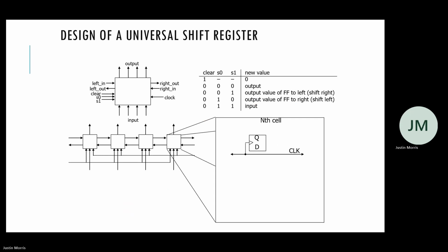All right. So here is another thing that we can make with our flip-flops. This is going to now be a universal shift register, rather than the other one where I'm only shifting right. This is going to be handling 1 bit, and we're going to connect multiple of them to handle more than 1 bit.